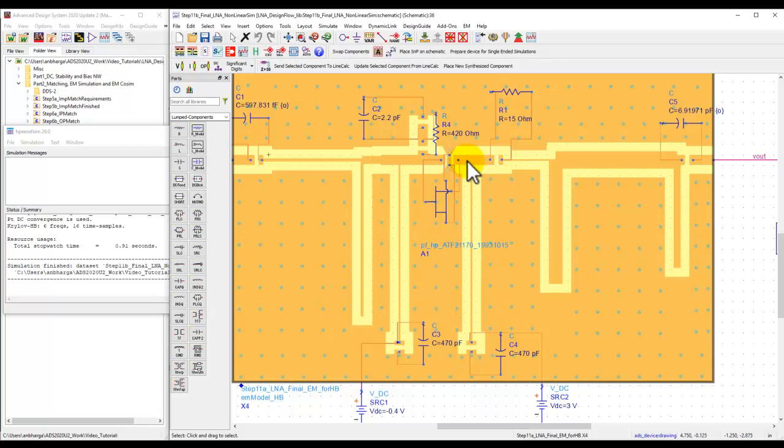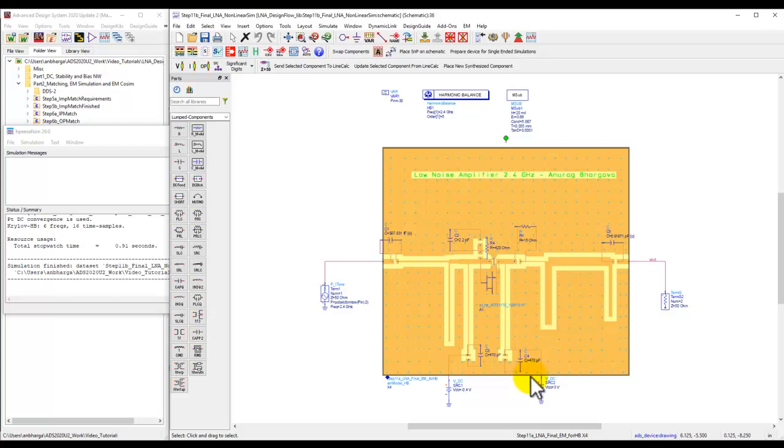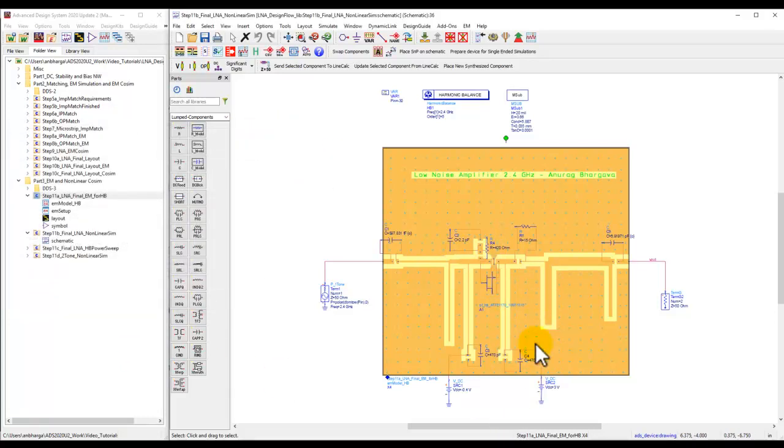So even if I have the impedance matching network, which will reject the second harmonic, this guy will suck up the second harmonic, and through the relevant capacitor, it will go to ground. Although right now I don't have suitable high frequency decoupling capacitors. In your actual board, it's not only one capacitor; you may have 3 or 4 catering to different frequency bands. But this is how the second harmonic energy will go down. So this bias impedance line itself is acting as a natural notch filter for my second harmonic.